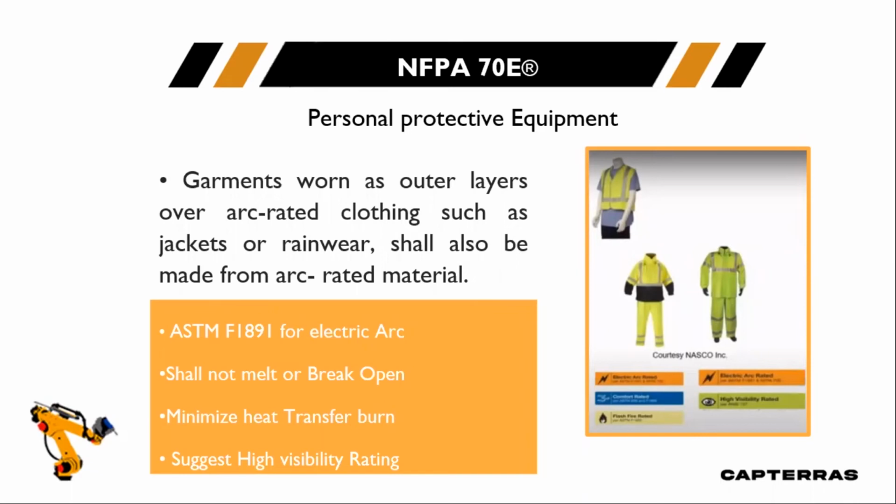As a note, garments worn should meet ASTM F1891 for electric arc, should not melt or break open. It also should minimize heat transfer burn, and it must have a high visibility rating.